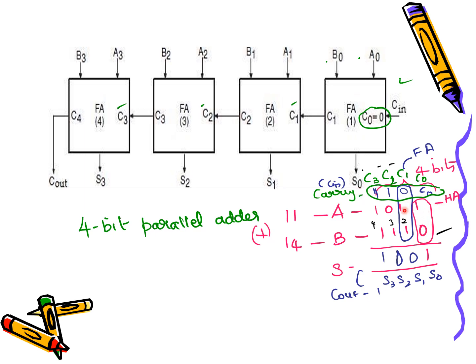Next is what? The next bit of addition is what? 1 plus 1, and the previous carry was not generated, so 0. So 1 plus 1 is what? 10. So sum is 0, carry is 1. Here the carry got generated from this stage and it got propagated to the third bit of addition. So now for the next consecutive stages of addition, you will or you may not be performing 3-bit addition. So to perform the 3-bit addition, you need a full adder.